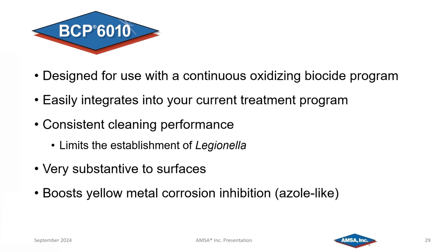It has an azole like property. And again, when the system is kept to a very high level of clean and there are low levels of biofilm deposits in the system, you're not allowing them to regrow to the rate where it needs to be cleaned on a regular basis. You get the best bump from that film forming characteristic of the product.